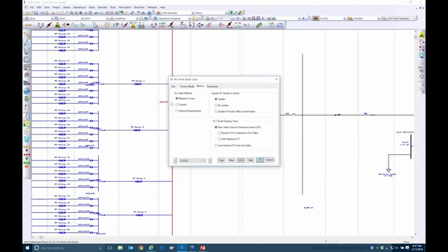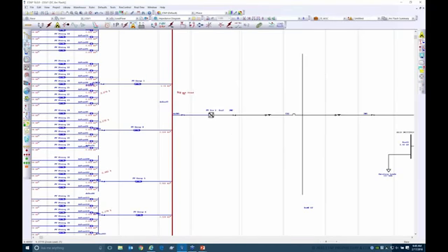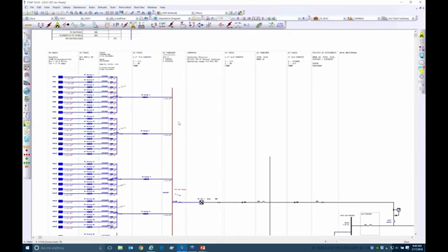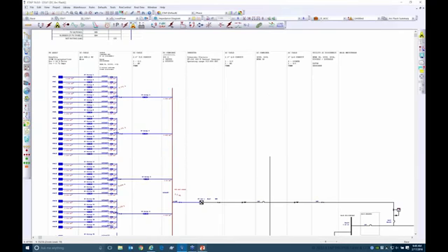And you can actually use the DC arc flash with the protective devices as well, just like the AC arc flash module, to calculate the arcing current, the fault clearing time, incident energy, and so on and so forth. Now, in my system, I've not set up all my protective devices appropriately, so we will essentially not get an output, but we do see what the fault current levels are over here.